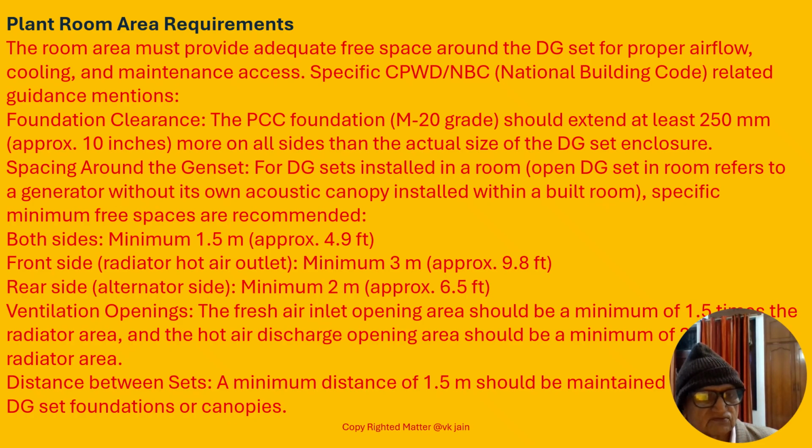The PCC foundation should extend at least 250 mm more on all sides than the actual size of the diesel generating enclosure. Spacing around the generating set. For a DG set installed in a room, open DG set in room refers to a generator without its own acoustic canopy installed within a built room. Specific minimum space requirements are recommended.